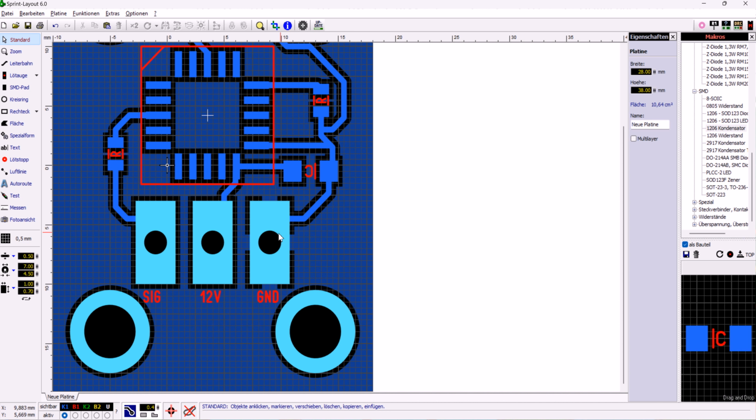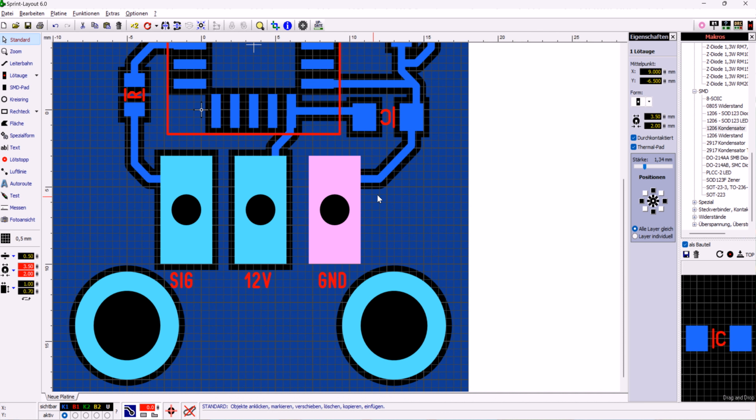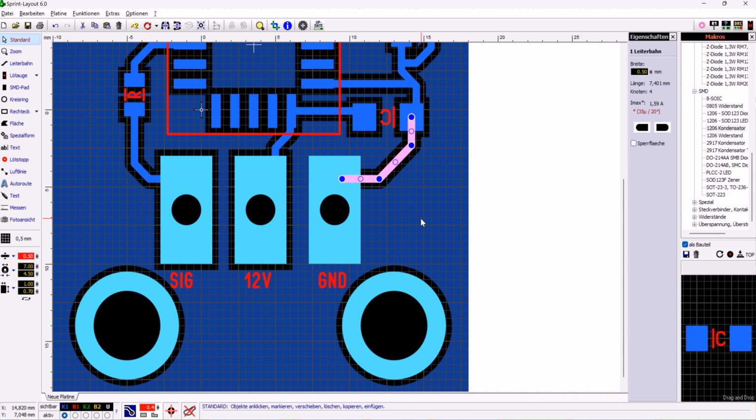The difference is with just setting the clearance to 0, I can even do it if it's still selected a thermal pad. Of course I have the best possible connection to ground. We also of course have to remove that trace. But it has one disadvantage, and that is copper of course is a very good heat conductor, and when you're soldering in this case a wire to that pad, in this configuration you would take quite some seconds, maybe longer, to solder a wire on this pad than on that one, because a lot of the heat will be sucked away into the ground plane, because the copper goes on, and there's no isolation, I would say, because the epoxy of the PCB is not connecting heat very well, but of course the copper is.